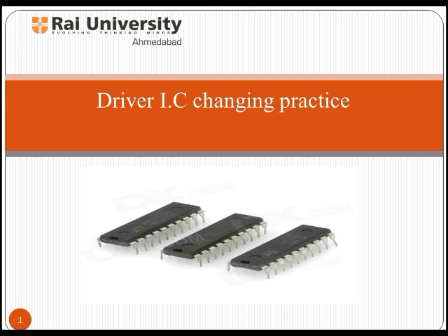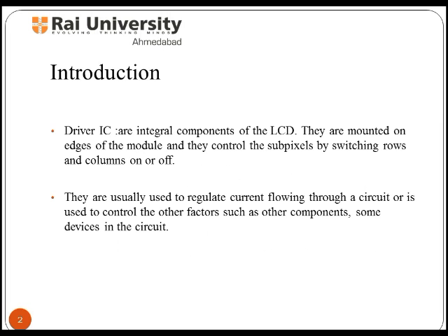We start with understanding this term first. Driver ICs are an integral component of the LCD. They are mounted on the edges of the module and they control the subpixels by switching rows and columns on or off. They are most commonly supplied in two types of packages: TCP, that is tape carrier package, and COF, that is chip on film. They perform the function of regulating current flowing through a circuit, or they are used to control other factors such as component sub devices in the circuit.